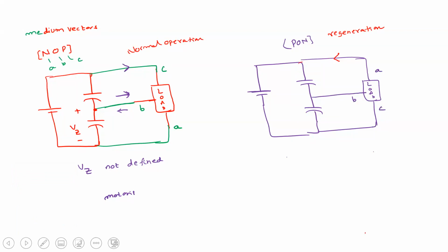Okay. So here also, right? In the A phase, the current is moving away from the A phase. So therefore, the return path is provided by B phase and C phase. So it may be any one of the phases or both phases. Therefore, here also the neutral current may flow in this direction or in this direction. So that means this Vz is undefined.